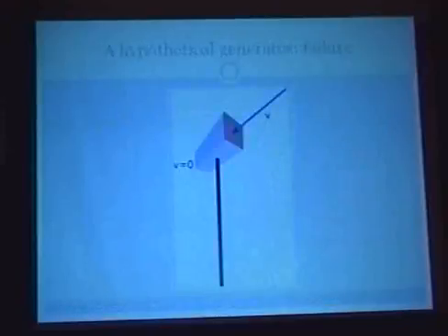So let's think about how much power such a device can extract from the wind. So I said that the power embodied is the velocity cubed. And you might think that what you want to do is build a device that takes wind of some velocity v and slows it down to 0. That is, it takes somehow all the energy out of the wind. So say you produce such a device, you put it on some mast and you put it inside some box. So there's some black box that takes the incoming wind, takes all the energy out of it, slows it down to 0 velocity. Well, if it's 0 velocity on the backside of this box, you could just close the box or do something.